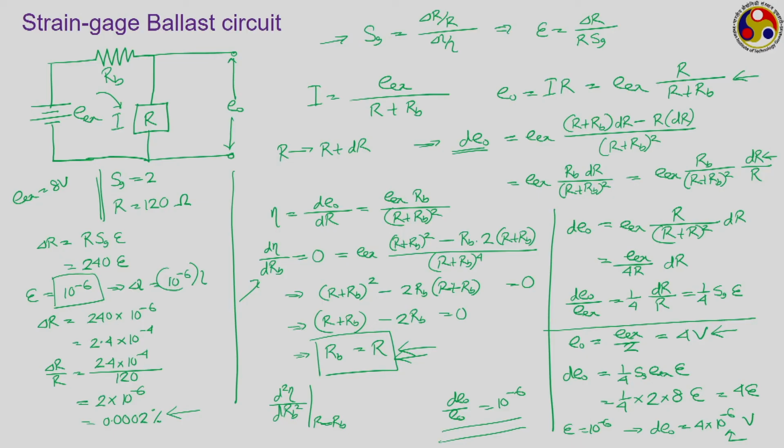While it is a very simple arrangement, quite similar to the potentiometer, using this we generally demand a very high voltage requirement, and therefore it is not always the preferred option in industrial application. However, if we are looking for some kind of dynamic arrangement, this can be preferred, because there we are not looking for the absolute change in strain, but trying to get a profile of the change in strain. Sometimes this can give good readings, but that is beyond the scope of the present discussion.